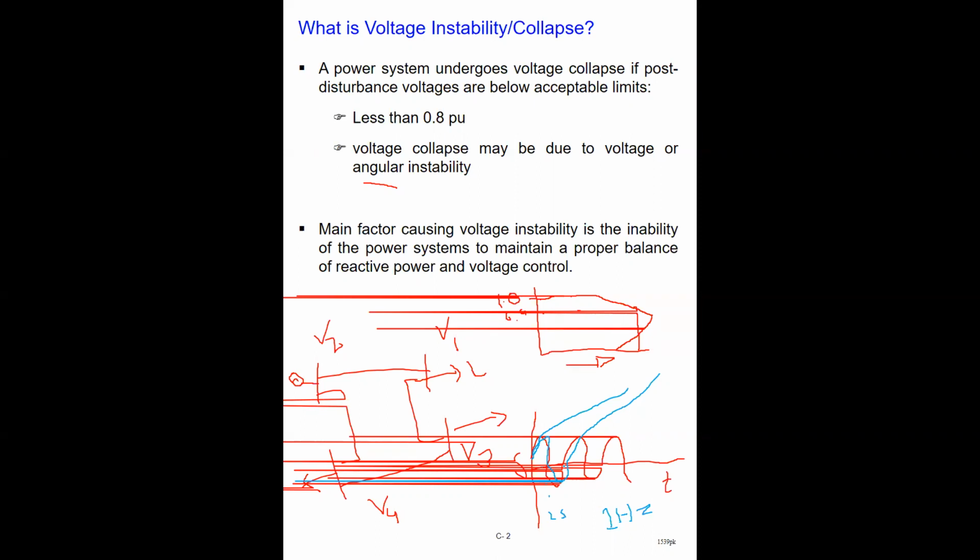And thus that means if I say after one cycle the instability takes place, let's say due to some severe disturbance, then after 1 second, instability will arise. So when you talk about the rotor angle instability, it is of a much shorter time frame. 1 second, 2 seconds, 3 seconds, or maximum 4 to 5 seconds, instability may arise.